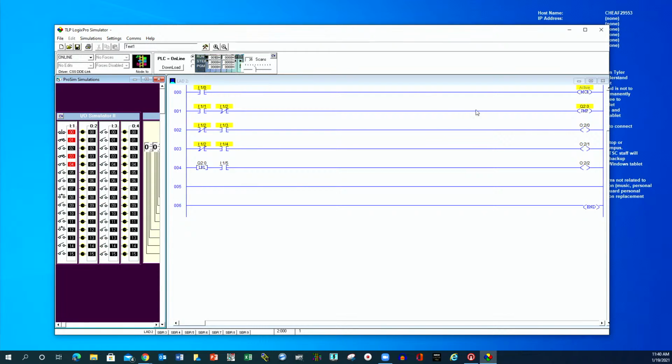See, it's true. My MCR is active. Why do you think it's jumping? You disable it in that whole zone. No, it is enabled because this line is true. Right, but when you make it not true. Oh wait, you know what I didn't do. No, but I'm actually jumping over. I'm completely jumping over all that stuff there, so it's not even scanning it. That's why it's not turning on. I just noticed I didn't add the other MCR fence. Yeah, I was going to say it's inside that block, right? So it's not going to chain it off. Yes, you're exactly right.